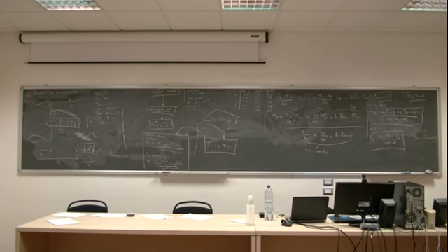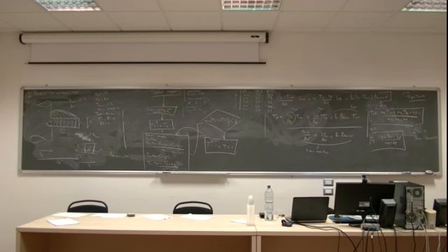But it's important that you understand the concept, because you can apply it to any physics. Now we have applied it to temperature, but you can apply it to acoustics, mechanical strength, fluids, whatever. We have assumed that each node depends just on its neighbors. We don't know the neighbors, we assume them, and we evolve this assumption until it converges, and it will converge.